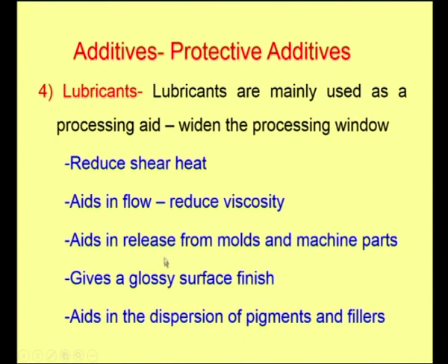Next, it aids in release from molds and machine parts. Not only during the process, but once the mold collects the melt and it solidifies, then this has to be released. It also gives a glossy surface finish to the final product, and it aids in the dispersion of pigments and fillers as well.